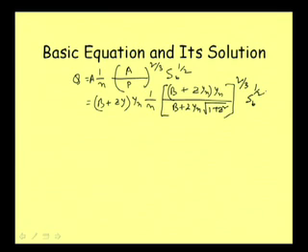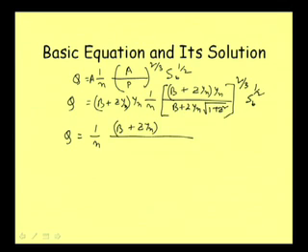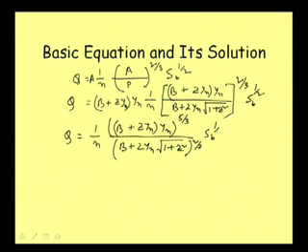Well, now in this expression, let me put all y as y n, and then it is Q. Q is equal to 1 by n, and we can write B plus z y n into y n, and then whole to the power 5 by 3, just multiplying this by that, and then here it will be B plus twice y n root over 1 plus z square and whole to the power 2 by 3, S b to the power half.